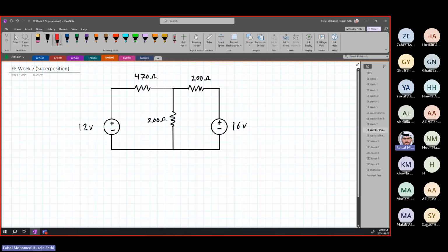We used to use nodal. How did we do nodal? We used to set a voltage V here, and then we had a ground over here. We would set our ground voltage. Ground voltage basically means V0, which is equal to 0 volts. And then we would start applying KCL at this node, the node in the middle here.